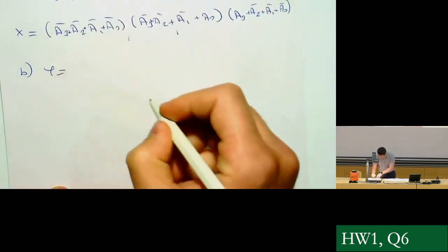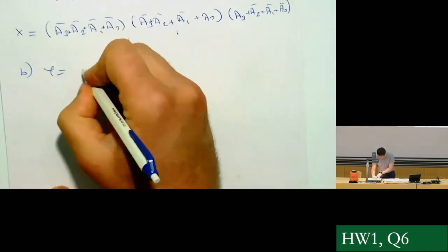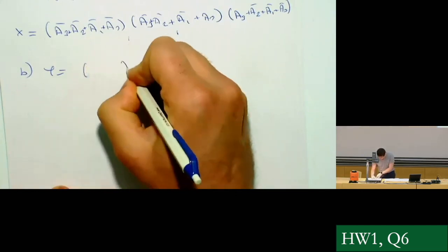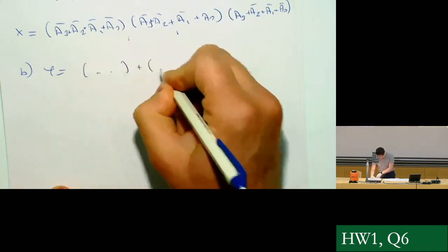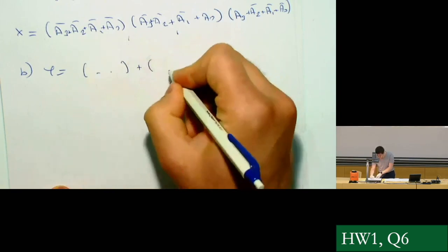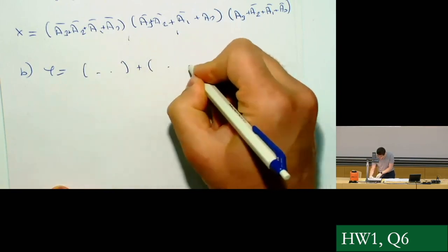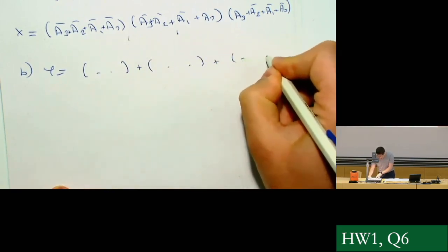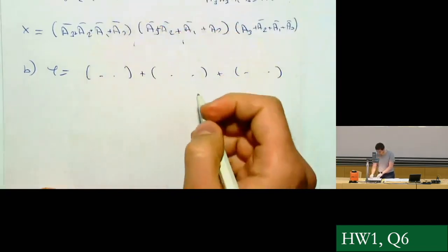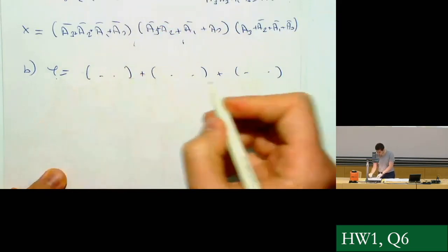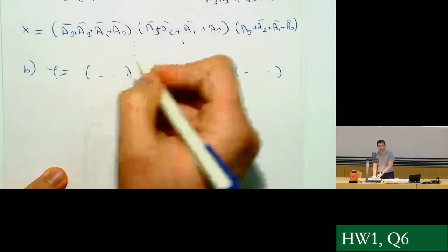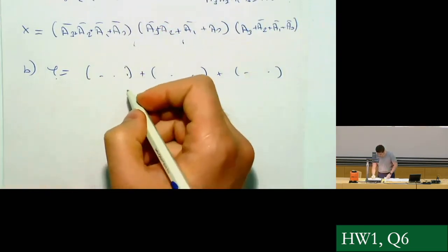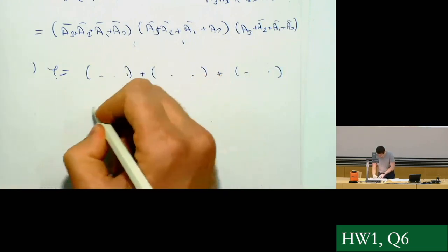So what is sum of products is basically I have terms, those terms are ANDed, and outside those are ORed. Right? So in other words, y is 1 if one of these is 1, basically. So let's then write it in that way.